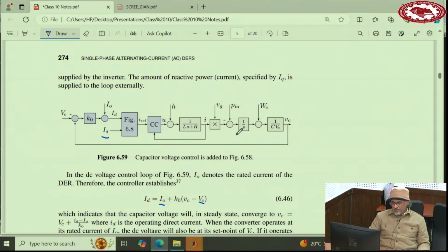So basically, from the energy, here is energy. We linearize the energy function. We have linearized it before. So this is the linearization of the energy to the voltage, this part. And the voltage goes back here, feedback, and then the current feedback loop. So this part we have already designed, and we know how to do it perfectly, no problem.